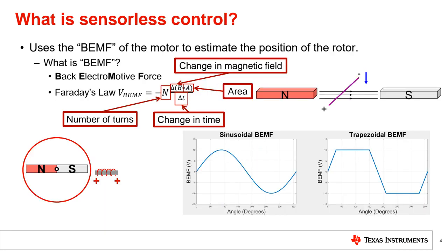Okay, what is sensorless control? This control scheme uses no position sensor, so it must estimate the rotor position in relation to the stator by using parameters. How can we detect the rotor position relative to the stator? Winding resistance or back EMF determine where or when to commutate the motor. We need to know back EMF. What is back EMF? I mentioned it briefly at the start of the class.